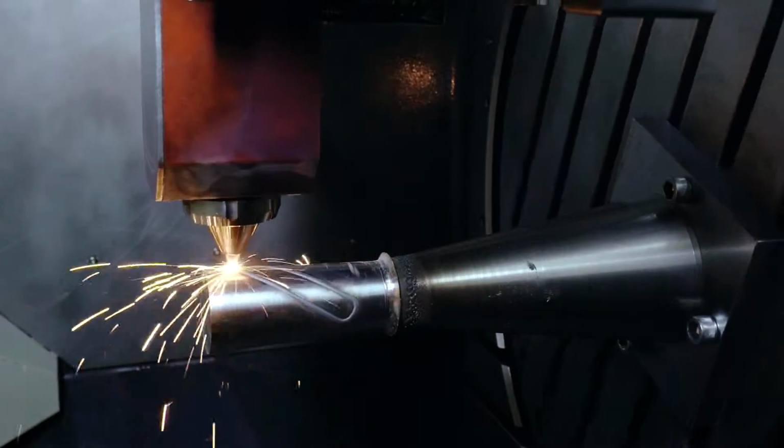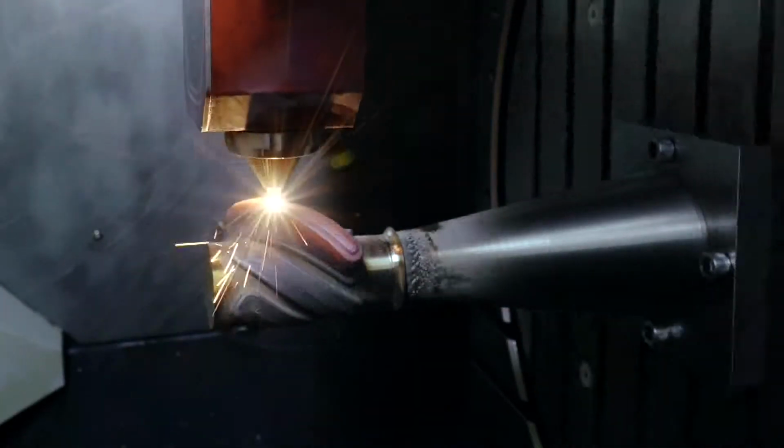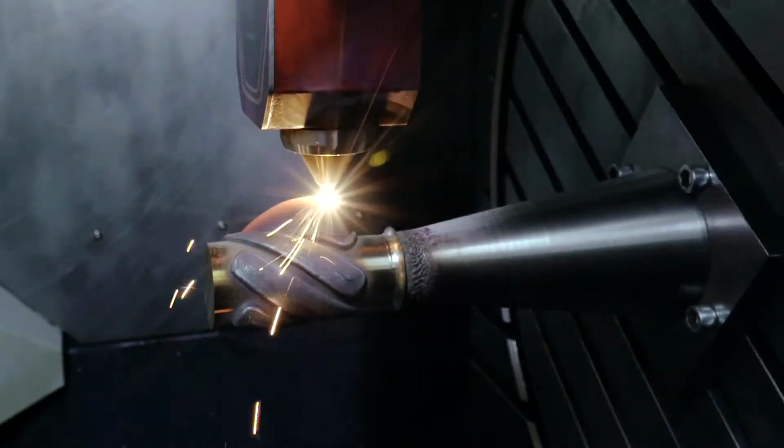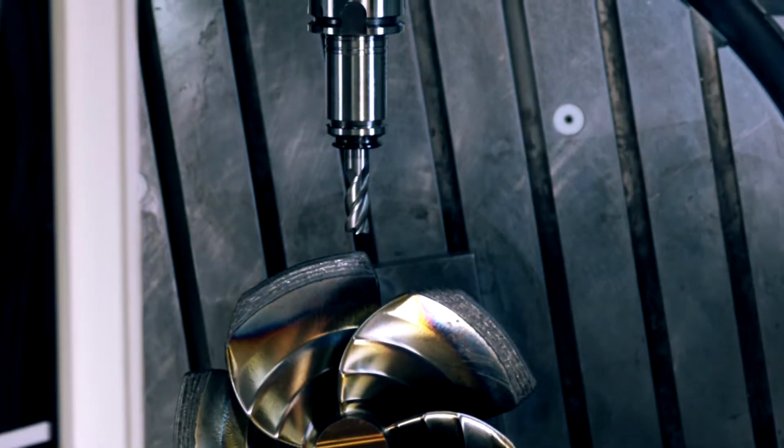In general, the laser cladding process for additive manufacturing provides the benefit that we can apply a huge amount of material within a very short time. This allows us to quickly produce components three-dimensionally, thus achieving superior productivity. This concept is fascinating as we use a coarse additive manufacturing process, and the accuracy is ensured by a milling application. This hybrid manufacturing process is ideal for us.